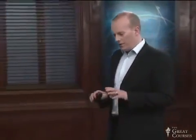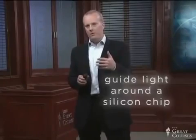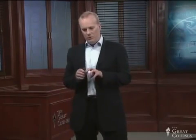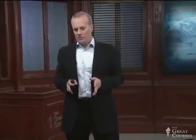There's a lot of exciting work going on in exactly this area, and there's a couple of pieces to it. One of them is to be able to guide light around a silicon chip in a manner where it's not lost. It's just like in the fiber optic case. And in order to do this, researchers have recently discovered how to use existing electronics processing, so things like photolithography and etching, which are already utilized to make electronic circuits. Well, they figured out how to make good waveguides out of silicon. And once they figured that out, they actually realized that silicon was an extremely good guide for light.